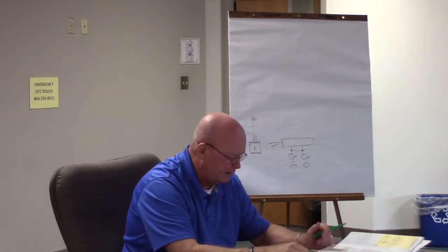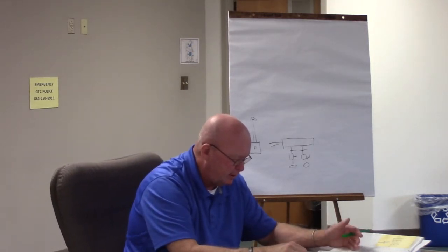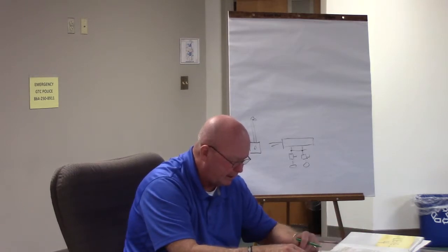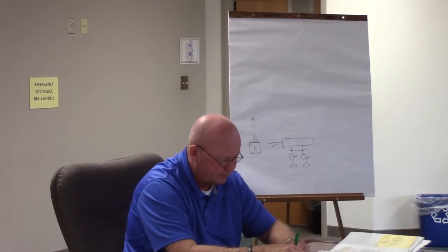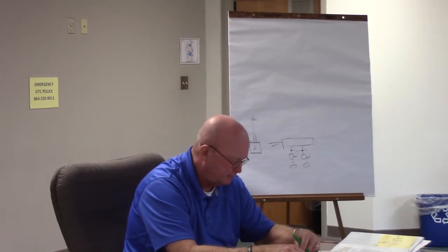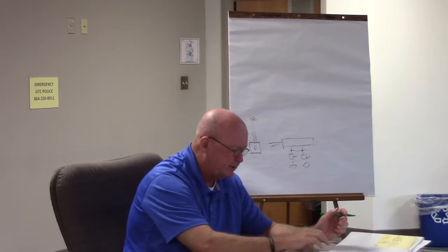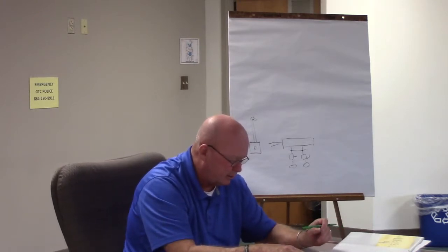Okay. Continuous duty load is a load that operates without interruption for more than blank hours straight. 3 hours straight. The conductor from the service point to the service disconnecting means is called blank blank.